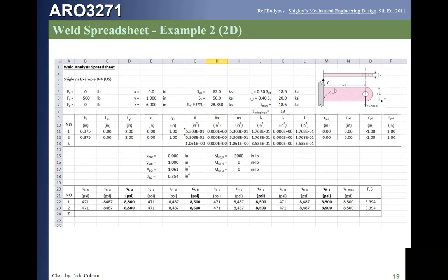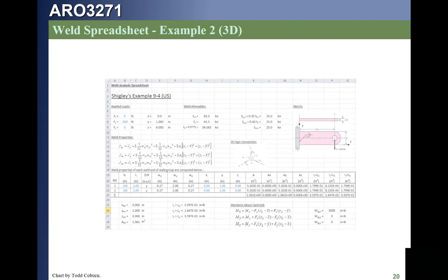This weld looks like we have this indicator says we've got 2 fillet welds. They're back to back, but they're along the vertical dimension of the plate, the 2 sides of the plate. What this is, is a snake bite weld loaded out of plane. We can use the simplified snake bite procedure, or we can utilize our detailed approach as shown here.